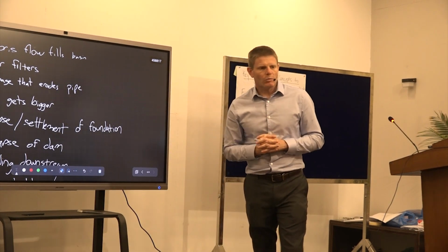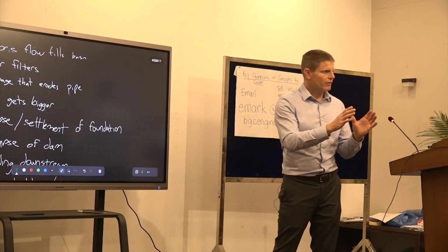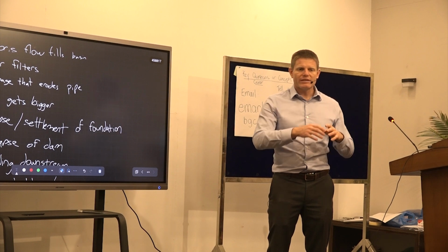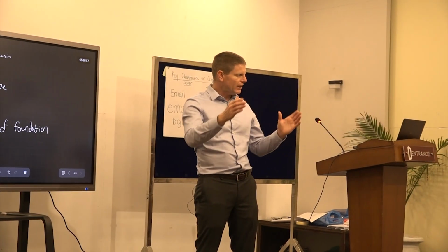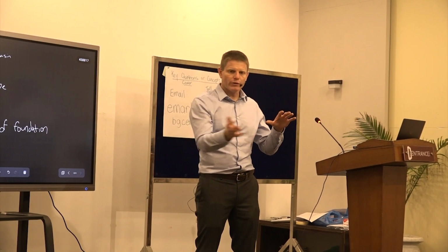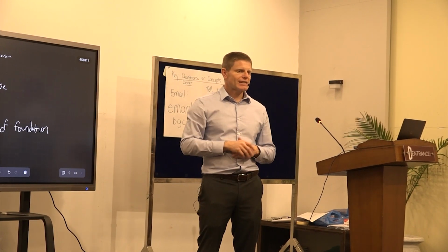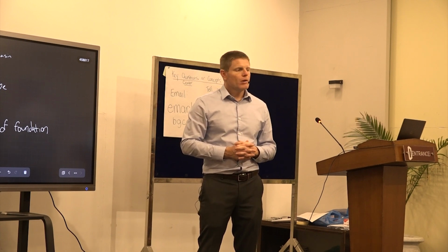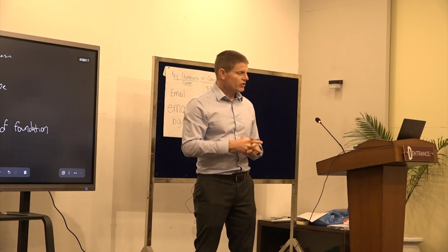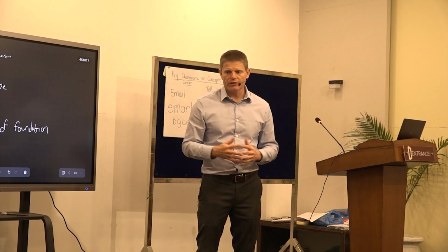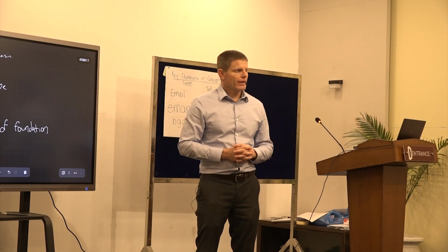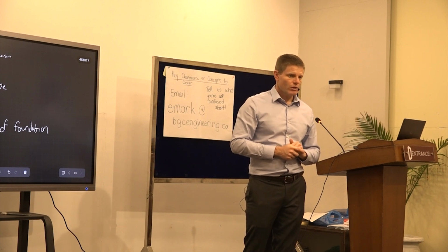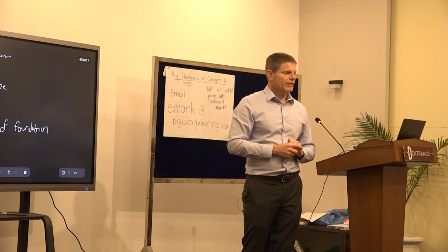So we do have methods. The methods exist. So that covers the impact pressures. But the other key component is understanding what is the discharge, right? So if you have a bridge opening, if you just have the 100-year water flow go through, that has a value, and you can estimate that value using common hydrology methods, right? But for a debris flow, the discharge is going to be much higher than it is for a clear water flood, right?